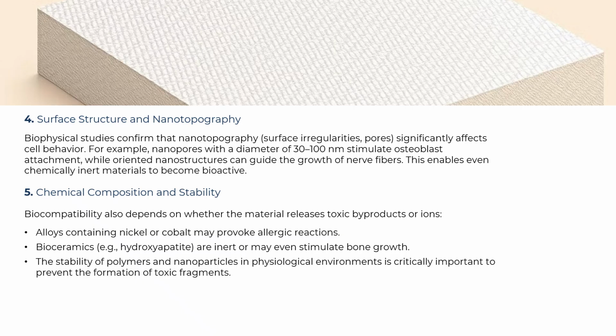Chemical composition and stability. Biocompatibility also depends on whether the material releases toxic products or ions. Alloys containing nickel or cobalt can provoke allergic reactions. Bioceramics, such as hydroxyapatite, are inert or even stimulate bone growth. Stability of polymers and nanoparticles in physiological environments is critically important to prevent the formation of toxic fragments.